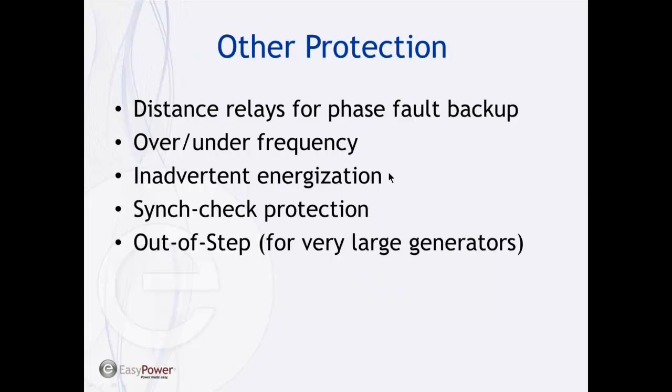All right, some other protection you may run into, and that's typically provided as an option or built into a lot of the new multifunction relays, some kind of distance protection as a backup phase fault detection. And this is going to be similar to the voltage restrained relays that we talked about, but you just use a distance element looking back up into the system to detect faults.